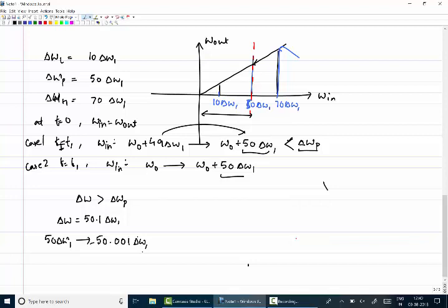If f of 0 is infinity, it's an infinite pull-in range. So that VC is there, which is changing your operating point. So the question which I just asked before: why is it able to lock in if you give a small step, but if you give a large step, why does it not?